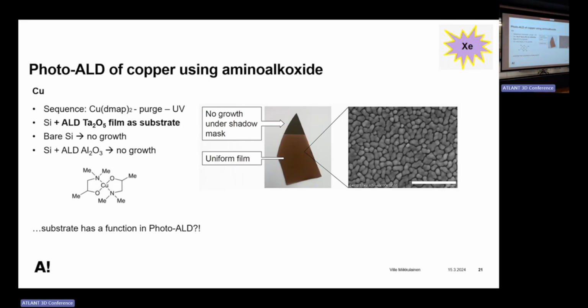Well, silicon is quite a good heat conductor, so I don't know how local that would remain. Well, people do laser anneal, for example in TFTs for panel displays. Yep, for decades. But if you want to do patterning with a UV laser with photochemistry, then you can get a lateral resolution of 1 micron or below, whereas if you use it just to locally heat up, that will decrease the lateral resolution. Yeah, both are possible.